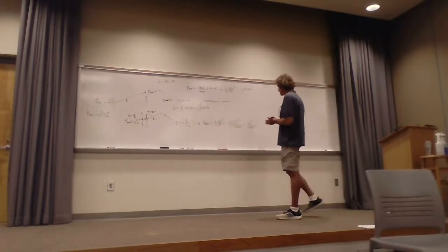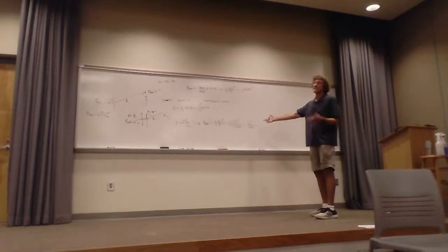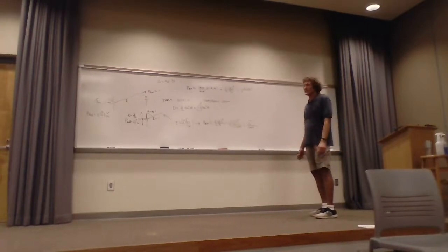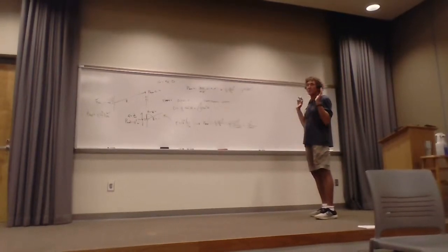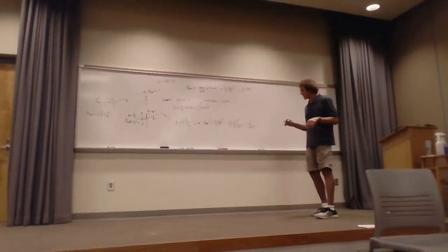We got this, right? That's the E field. Now think about what I asked. What's R? Sorry, this is the power density. How do you get the power density from anything? Any antenna? You always take the total power radiated divided by 4 pi r squared. You get the isotropic power radiation.